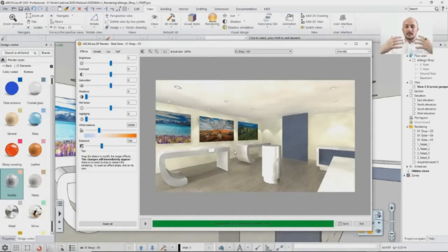Okay, so let's bring in a little bit more details. So the second step is bringing in details, test them, whether they look like you wanted, and then when they are, then just bring in more details, more details, more details. You will see that rendering will gradually slow down because you will have more surfaces, and this is where the fifth key factor, the complexity of the model, comes in. Whenever you bring more and more details into the model, it will slow down the rendering process because this virtual eye, the camera, the render itself will see more surfaces.